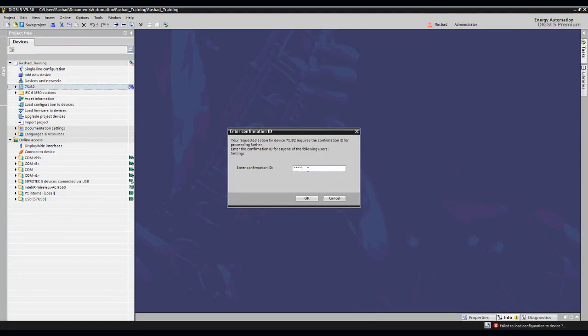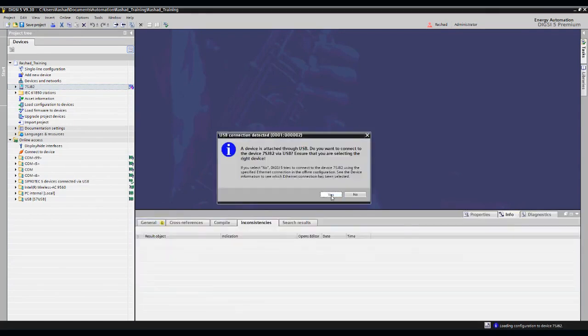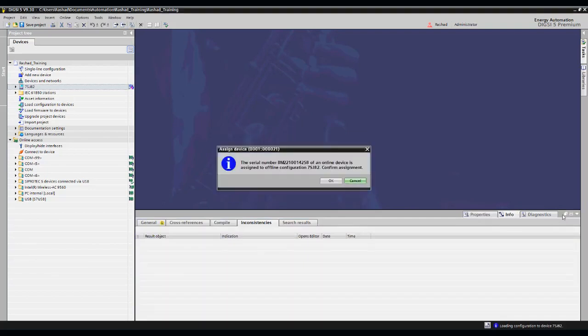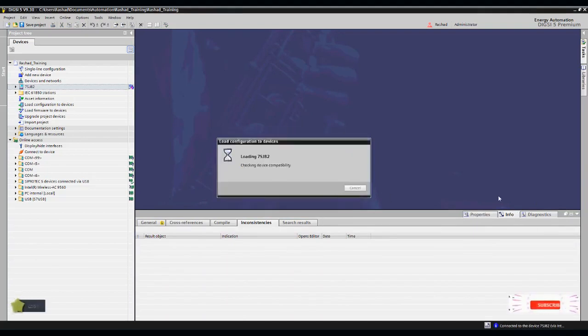Of course, the password, even in SIPROTEC 4, you were able to change it, but let's say by default in every relay, it remains like that. So let's not change it and leave it as it is. 6 twos. Of course, as soon as you send to the relay, what will happen next is a restart for my protection relay.